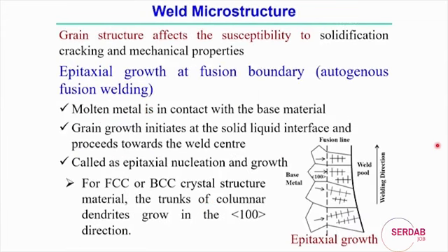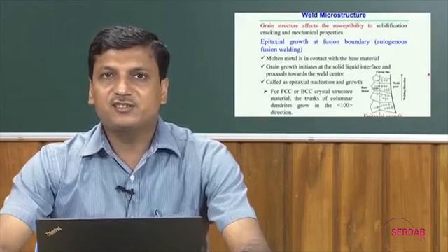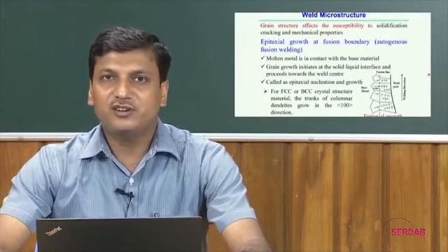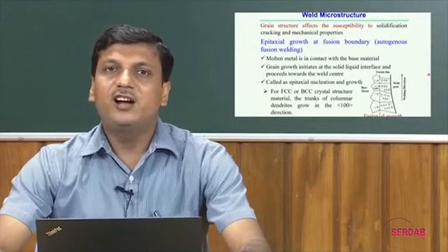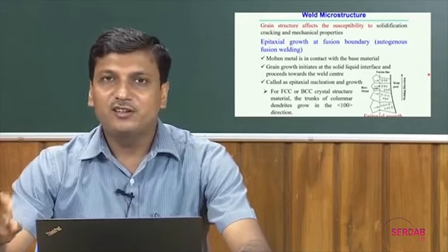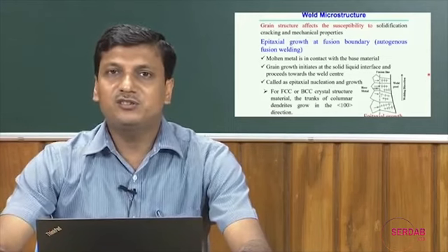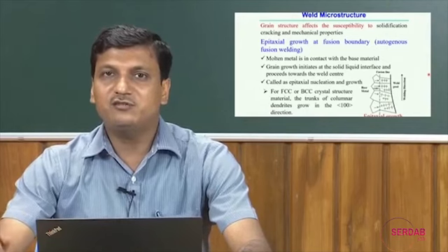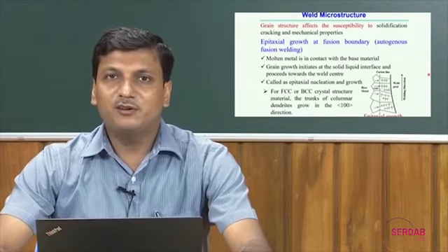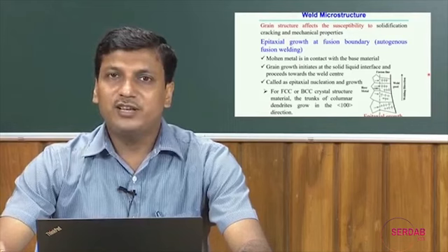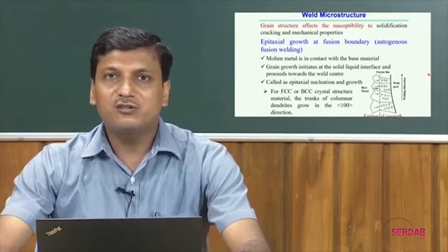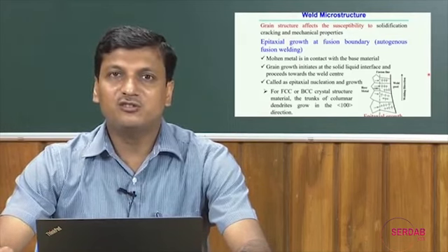Now, after the solidification mode, we will look into the discussion on the weld microstructure. Grain structure affects the susceptibility to solidification cracking, and it is also very much linked with the mechanical properties. So it is necessary to link the final microstructure with the expected mechanical properties, and whether solidification cracking may occur or not.